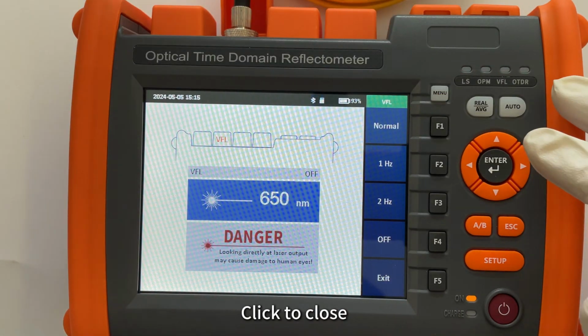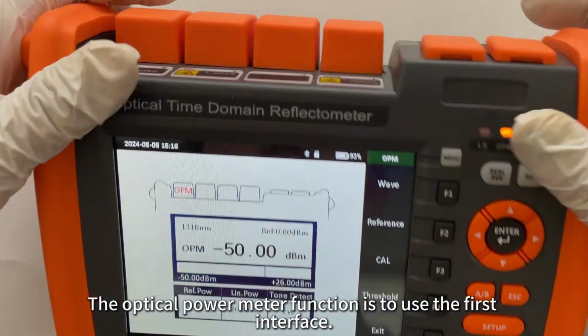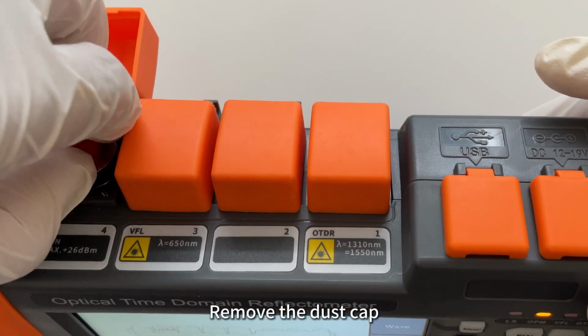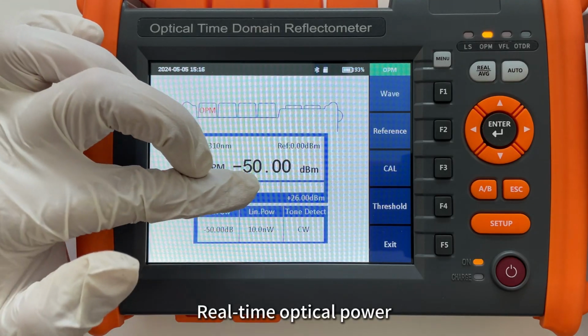Click to close. Let's introduce the function of the optical power meter. The optical power meter function uses the first interface. Open the dust cover and remove the dust cap. The main part of the interface shows real-time optical power.